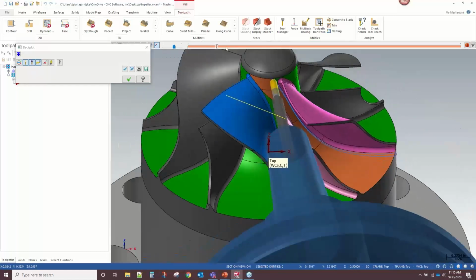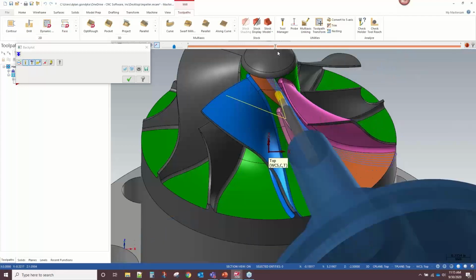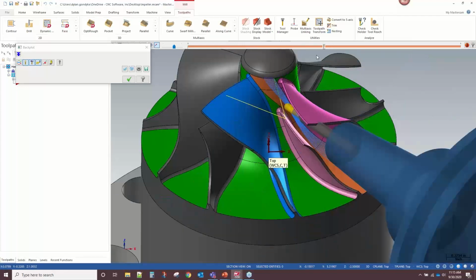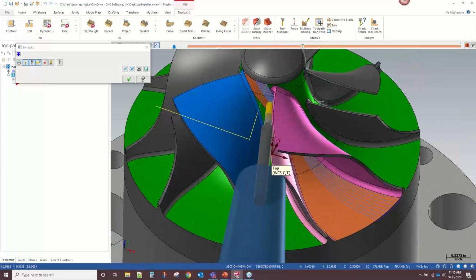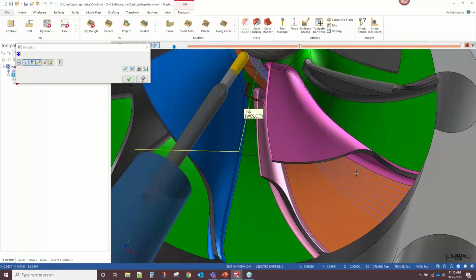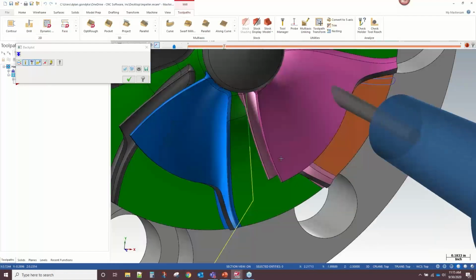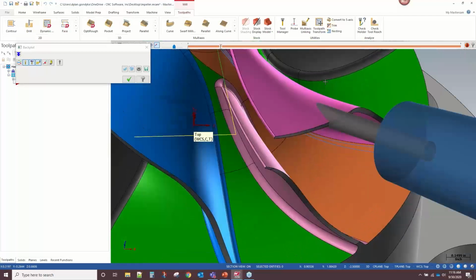But the actual tilt motion looks pretty nice. If I can just get it to go through that throat area, it wouldn't be too bad. If I just handed all of this off to collision control and I said tilt automatically however you think is best, it might make a mess of this because I've handed it something that, especially in this area here, it's not even close to a valid path.